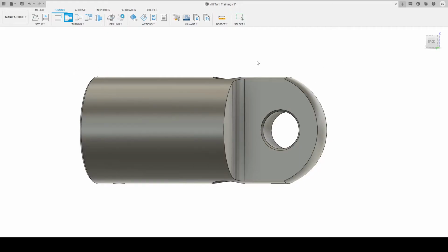The holder looks fine as well. We don't need to change anything here. You can, if you want to, change things, but for this case we're pretty right. Setup, if you want the tool orientated any way on the turret, you can do that, but for today that's fine, all standard. We're not doing anything too special. We can define our speeds and feeds.